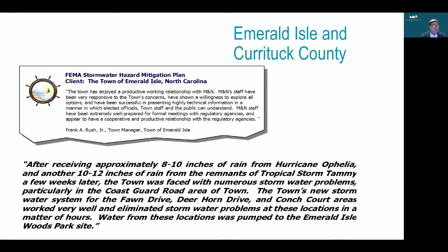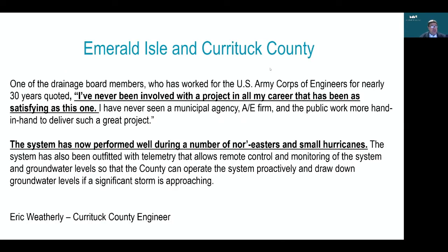These are a couple of graphics talking about the client's perspective. What we found in both of these areas is that what we can handle has been about 6 inches of rainfall in a 24-hour period. If we see much more water depth than that, it's going to overcome the natural infiltration capacity as well as what these pumps can do. But we're really pleased to see that they could be effective even to events up to that. That's between a 10 to 25 year rainfall event, even with the new statistics along eastern North Carolina.